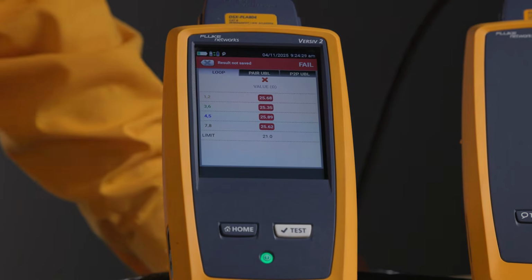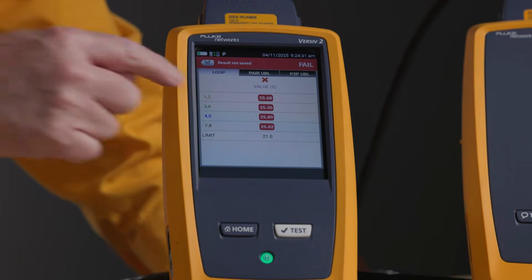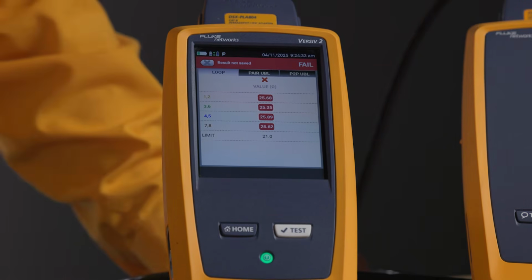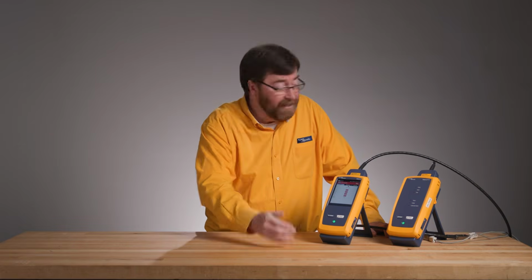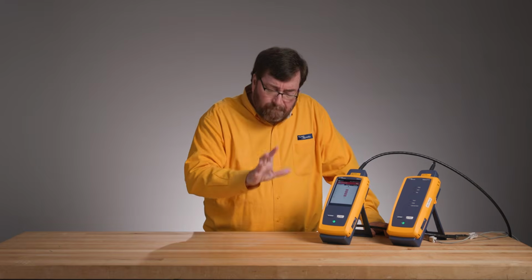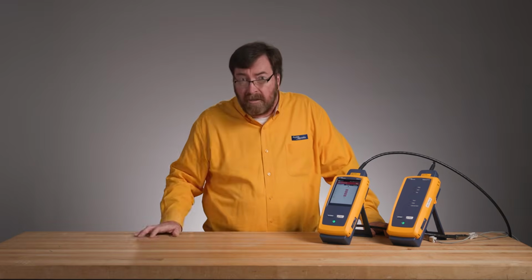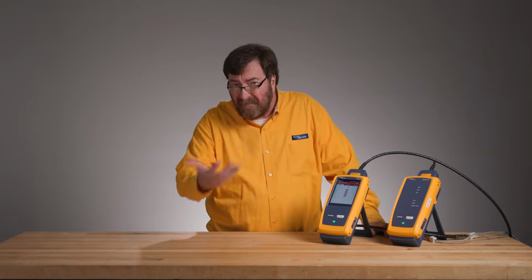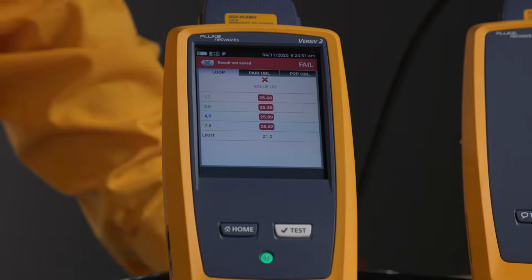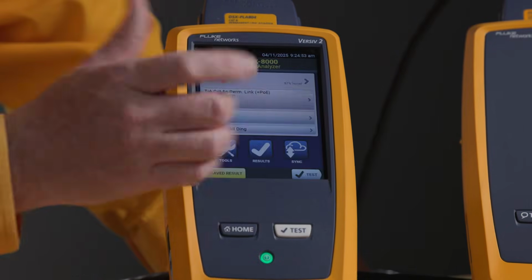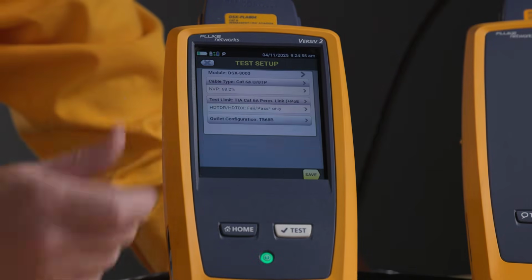The measured values are the same. We just didn't have a limit. Now that we have a limit, we see that this cable is exceeding the requirements for loop resistance. It happens to be a copper-coated aluminum cable. But to appreciate the change in the standard, the new definition of what the limits should be for loop resistance, we've updated the tester, and we'll find now, let's just go in and add a new test.